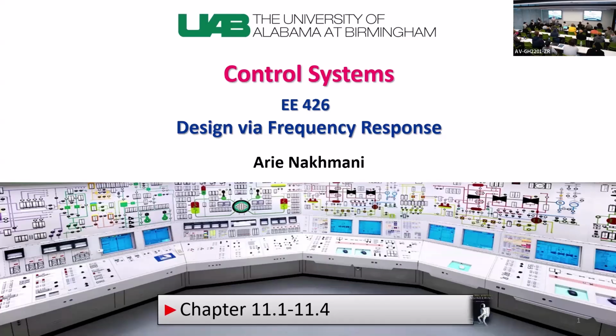And your goal is to stay focused because this is kind of a tough topic, a little bit difficult. You need to stay very focused on the procedures that we are going through. And I will show a few examples just to make sure that you know all the steps that you need to make. This is a little bit of an art because after you design it using these steps, you still need to refine a little bit. You need to move the poles a little bit, the gains a little bit, until you get the performance that you want from your system, because you will never get it exactly right.